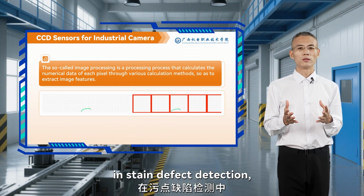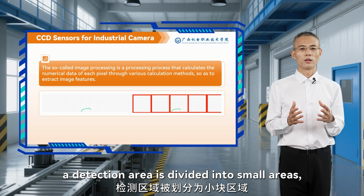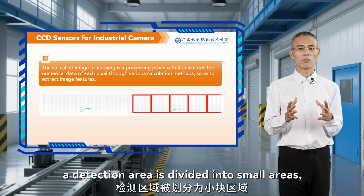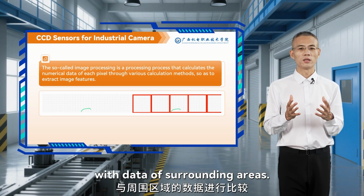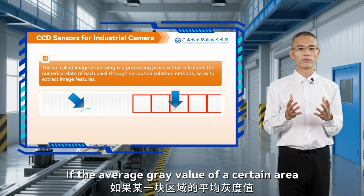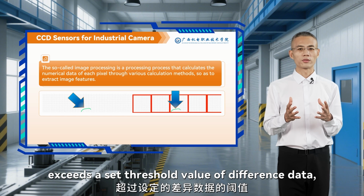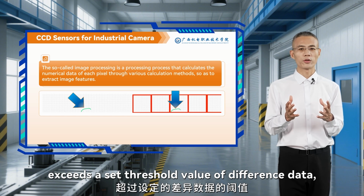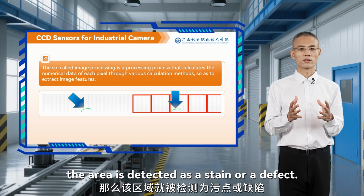For example, in stain defect detection, a detection area is divided into small areas. An average gray value in each area is compared with data of surrounding areas. If the average gray value of a certain area exceeds a set threshold value of difference data, the area is detected as a stain or a defect.